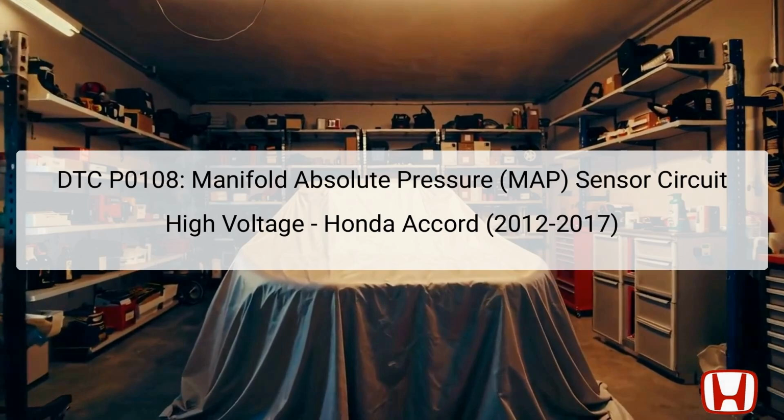The Diagnostic Trouble Code DTC P0108 refers to a high voltage condition detected in the Manifold Absolute Pressure MAP sensor circuit of the Honda Accord models produced between 2012 and 2017. This issue typically arises from the MAP sensor itself or associated components, which measure the pressure or vacuum in the intake manifold. The MAP sensor plays a crucial role in engine management as it communicates with the powertrain control module, PCM, to optimize air-fuel mixtures for efficient combustion.